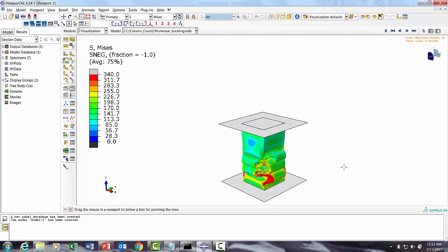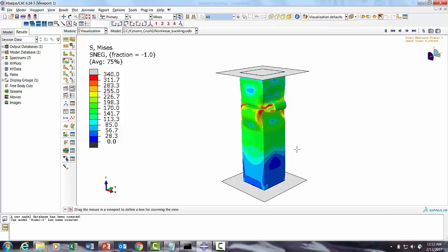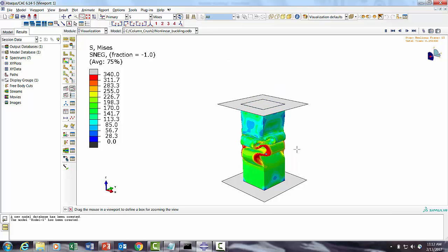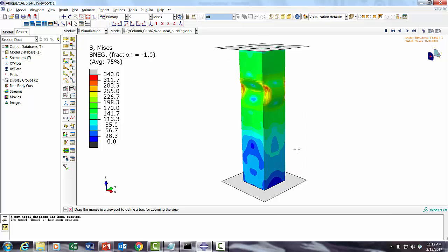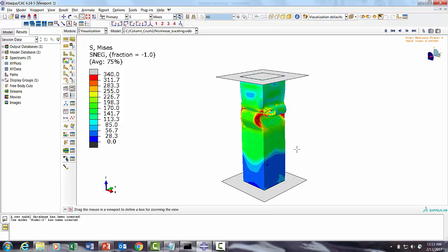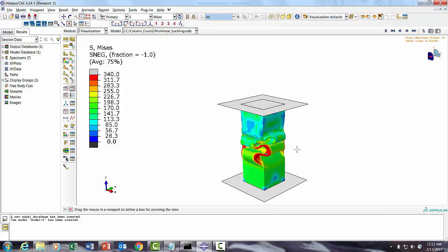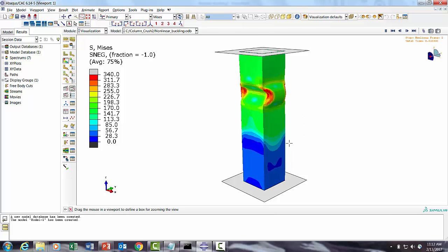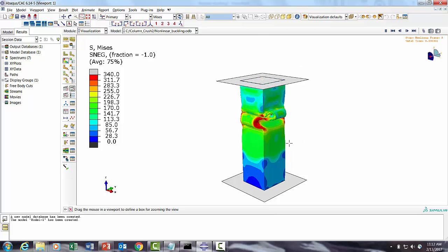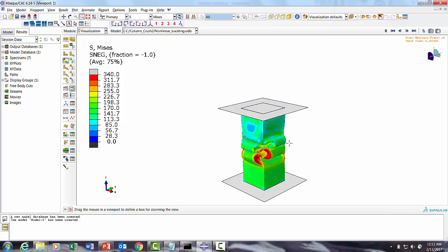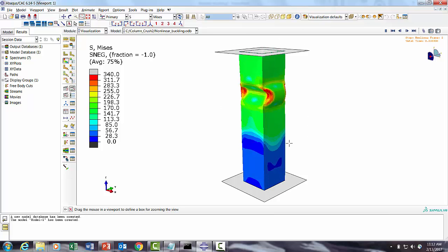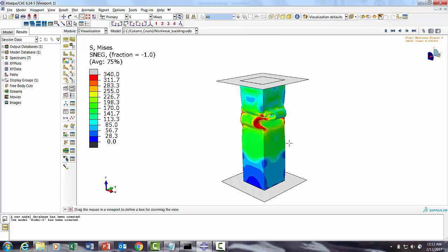Today's problem we are going to do a square tube crush test. This particular problem is actually a nonlinear buckling with capturing the post buckling behavior. Because you see our couple of videos on the nonlinear buckling side, we are not really capturing the post buckling behavior. We capture what is the maximum buckling load, and we are no more interested in the post buckling behavior.